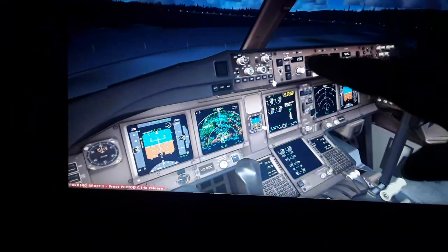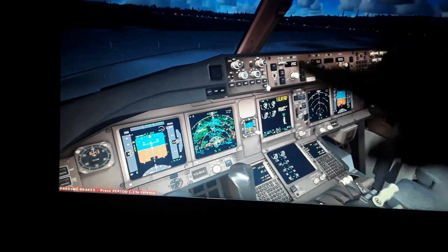So we're going to have a complete route using climb, cruise, descent, and approach procedures. I'm going to show you how to do that using the flight management computer, which is also interconnected to the autopilot and flight director system panel. Over here, the LNAV and the VNAV are going to use the FMC input. So we're going to have the guidance of the aircraft, either manually or automatically, for the flight plan using the LNAV and the VNAV, the lateral navigation and vertical navigation of the autopilot and flight director system panel.